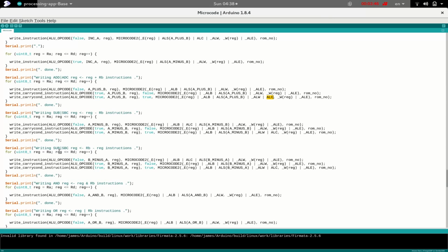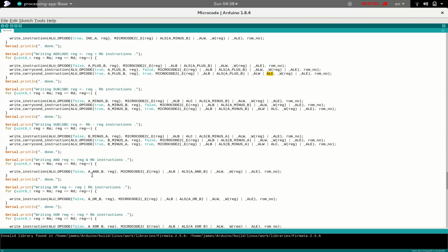So that too has a subtract and a subtract with carry, but this time the B register minus whatever register we've written in the instruction opcode. So again, this time it's the B minus A operation, but for the rest we have one version without carry. Of course it's a subtraction, so we'll always be setting the carry. But if we have a conditional on the current state of the carry, then we'll simply be carrying that over. So if that's false, we won't set it, and if it's true, we will set it. So that takes care of all the arithmetic operations, basically.